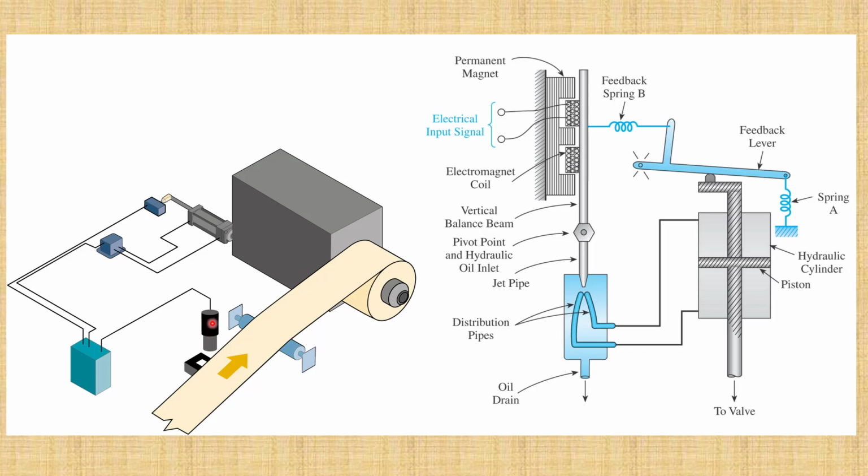It's a plus and minus power supply. So I'm going to calibrate this, set this up, so that when the edge is halfway blocking the detector, it's at 0 volts. That means if the edge were to move one way, because the wrap's waving in the process somehow, if the wrap moves one way, I'm going to get more light. It's going to cause the voltage to go up to a positive value. If the edge moves this way and I'm blocking more light, this voltage is going to change the other way